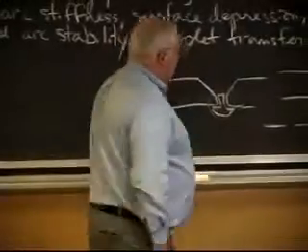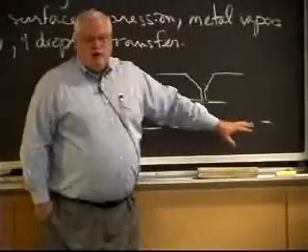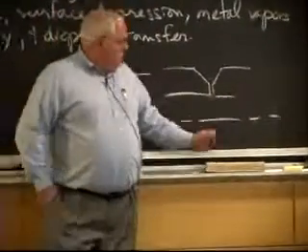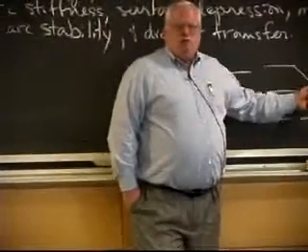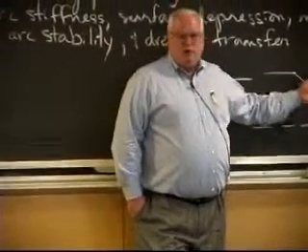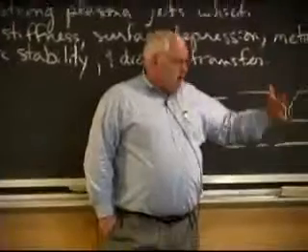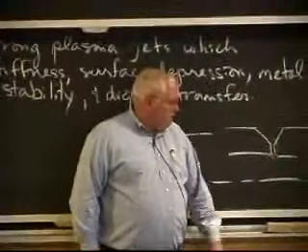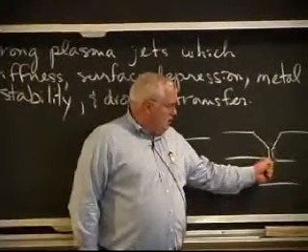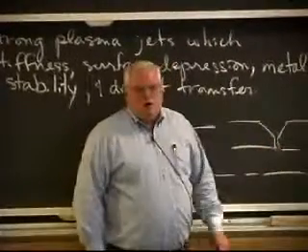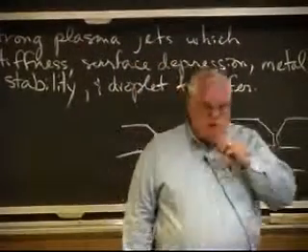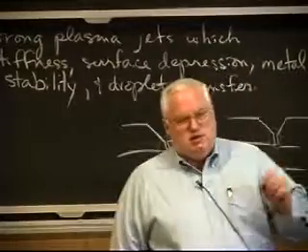Now it turns out, in the last 25 years, they have brought in some of these automatic machines. The automatic machines don't use inserts; they use gas tungsten arc welds for the root pass, and then the fill passes are gas metal arc. And because gas metal arc is more efficient, they can pay for themselves. However, the quality control technique they use on the manual welding of pipelines is this.